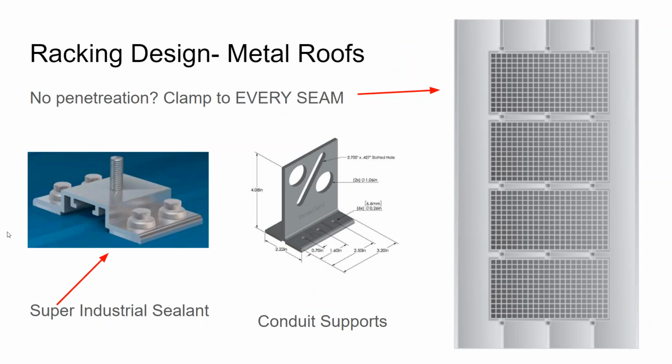Metal rooftops that aren't standing seam have screws that go directly through the roofing metal. And while it's kind of hard to see, there's this industrial sticky tack that goes around that penetration. I actually like this better than the standing seam solution. The reason is, as the installer, I can feel the lag screws biting into those purlins, and I know it's a solid connection, whereas with the standing seam, I have to rely on the strength of how the metal panel is attached to the rooftop. And so in terms of pull strength, going through the roof with a hole and a penetration is actually stronger than just clipping to the rooftop.